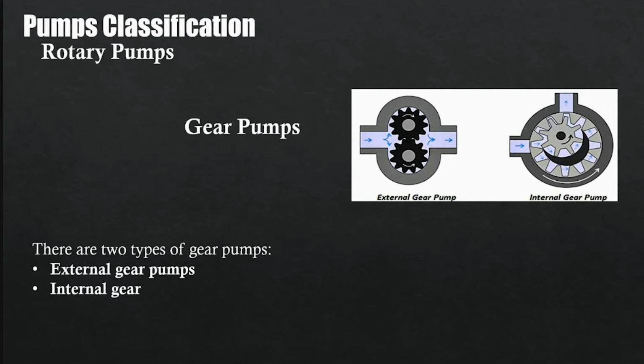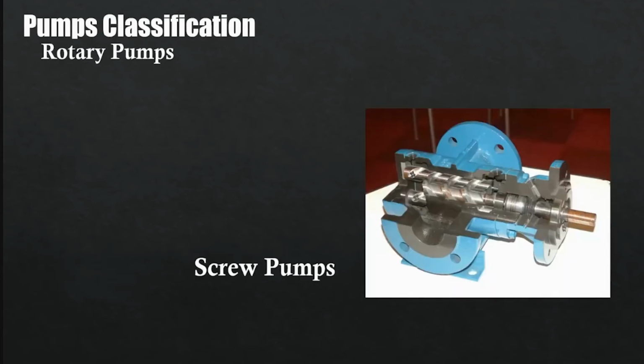The two types of gear pumps are external gear pumps and internal gear pumps. The external gear pumps have all the gear rotors cut externally. The gears may be square, single helical, or double helical, while the internal gear pumps have one rotor with internally cut gear teeth meshing with an externally cut gear idler. Pumps of this type are made with or without a crescent-shaped partition.